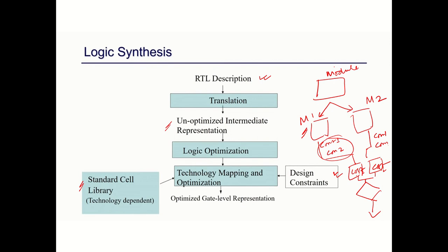Just consider that your constraint parameter is to minimize the area. In this case, we are not aware of the area directly. We are aware only of some product terms, or cell count, or transistor count. So in this way, we need to reduce the transistor count, cell count, or LUT count. For both of these realizations, we will realize the circuit and check all of those.